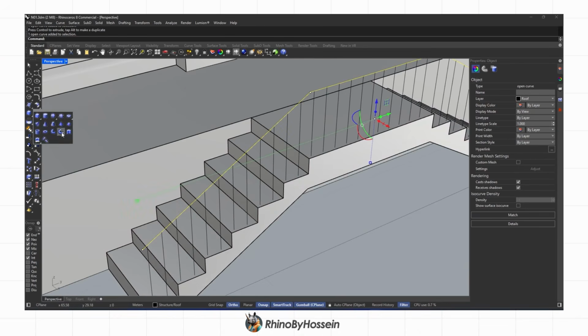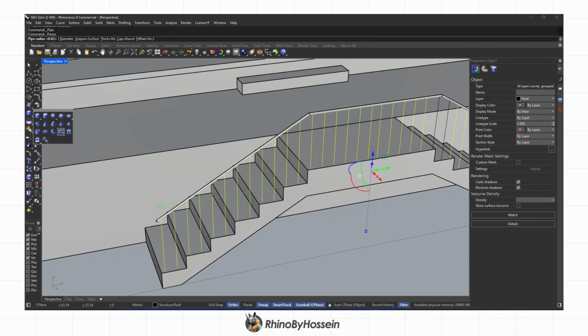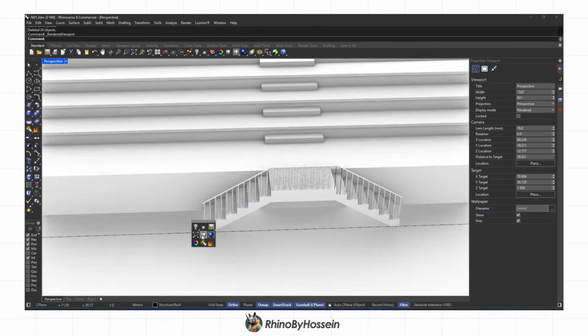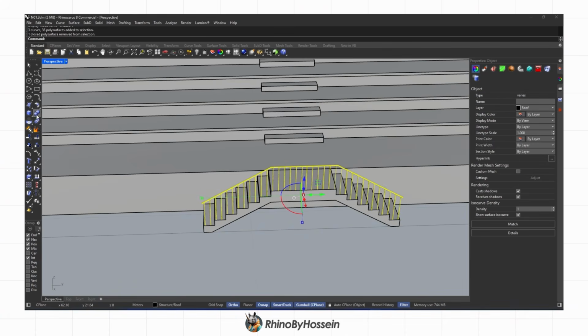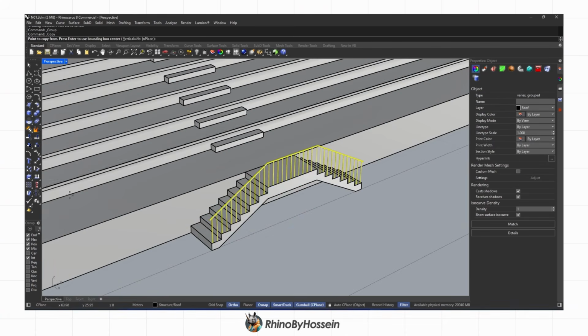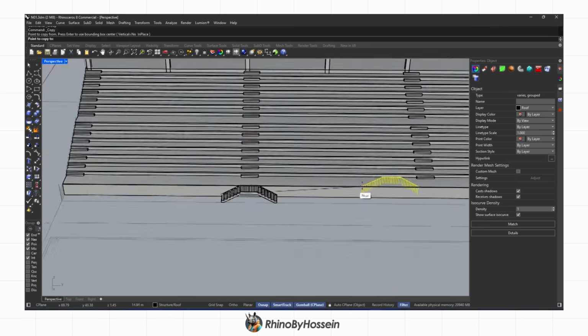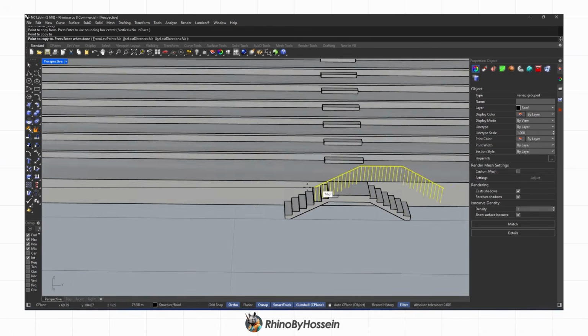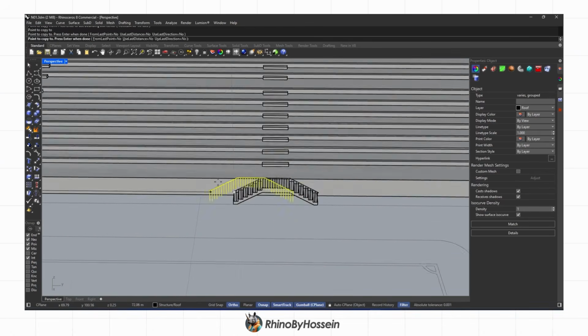For the internal railings, I use a radius of 1 centimeter, and for the main railing, I use 2 centimeters for better readability. Finally, I copy the railing along the stairs, placing one every 3 steps. And that's one way to handle railings directly inside Rhino.